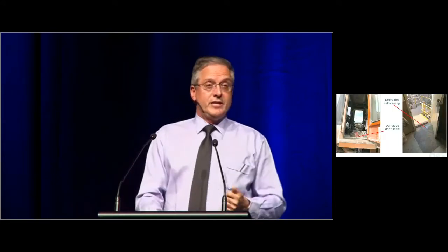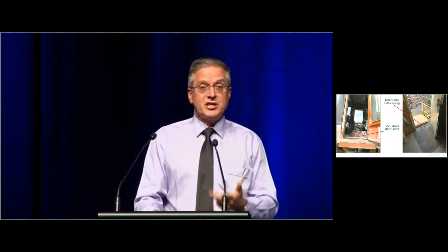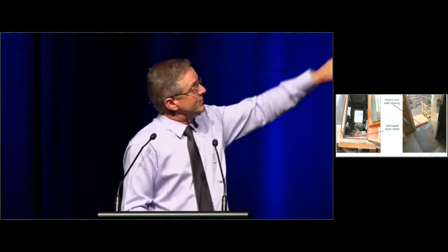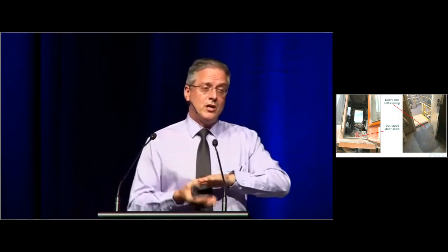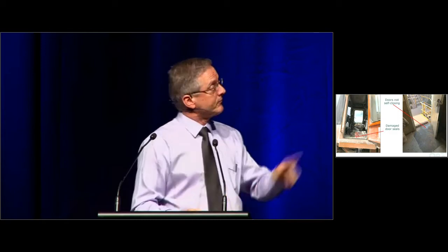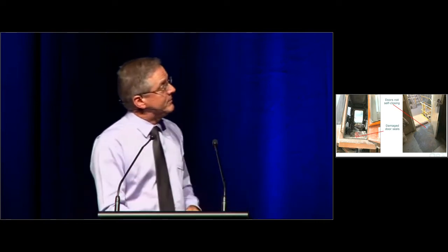Door seals in cabins, either damaged, missing or ineffective, especially with platforms where you've got the access platform right at the bottom of the door. You get material dropped on that, sits in the grate, and every time they close their door, they're smashing rocks in against the seal that damages it.